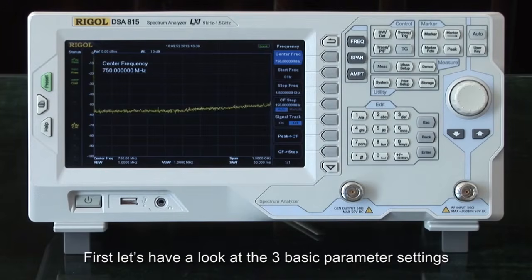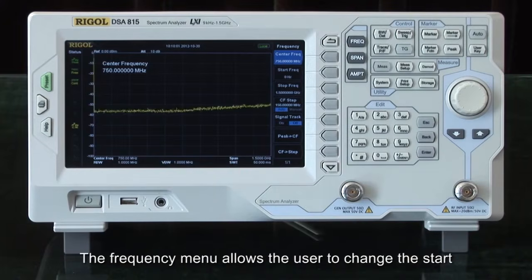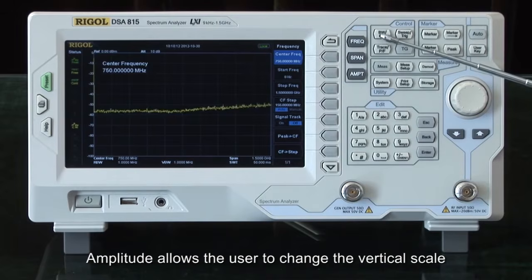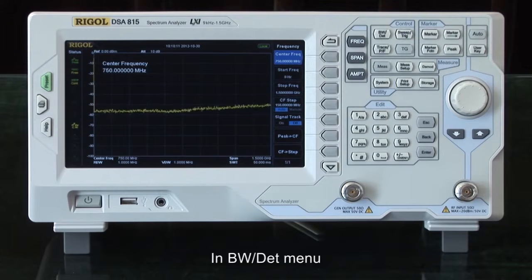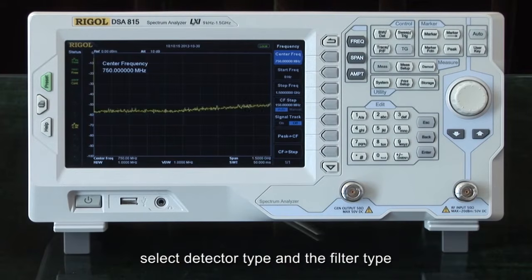First, let's have a look at the 3 basic parameter settings of frequency, span, and amplitude. The frequency menu allows the user to change the start, stop, and center frequency values, as well as other frequency-dependent settings. Span changes the frequency span that is displayed, and amplitude allows the user to change the vertical scale and units being displayed. In the sweep control area, we can set the sweep parameters of the analyzer. In the bandwidth detector menu, we can set resolution bandwidth and video bandwidth, as well as select the detector type and the filter type.